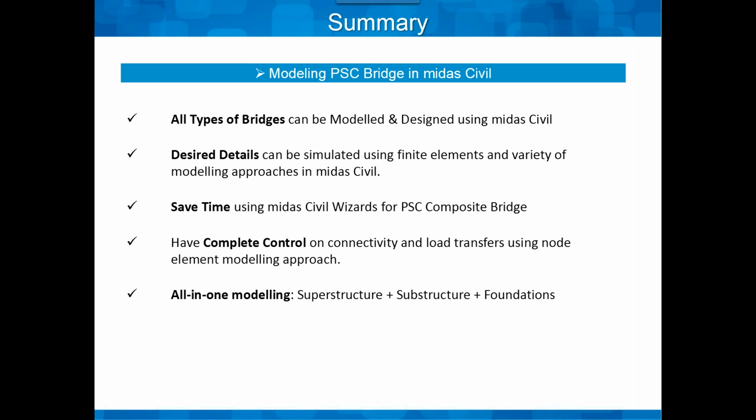Then you can also save a lot of time with the help of wizards. PSC Composite Bridge Wizard is available along with other wizards. You can have complete control on the connectivity and load transfers because we have a node element modeling approach in Midas Civil, unlike other programs where you have member-based modeling. So it's not a black box.